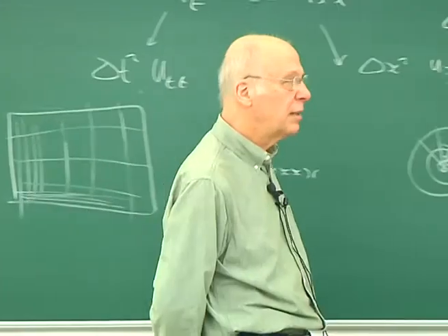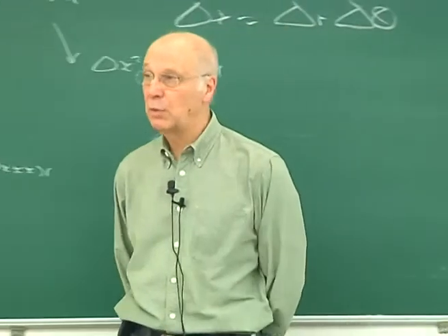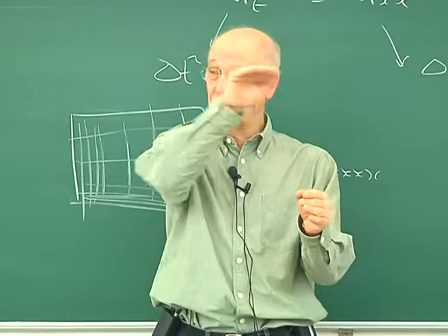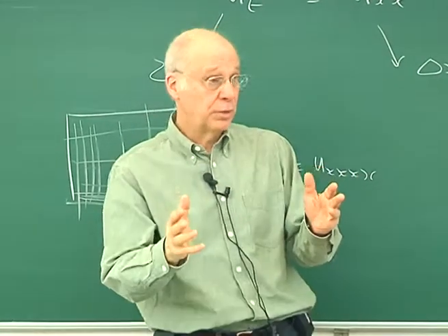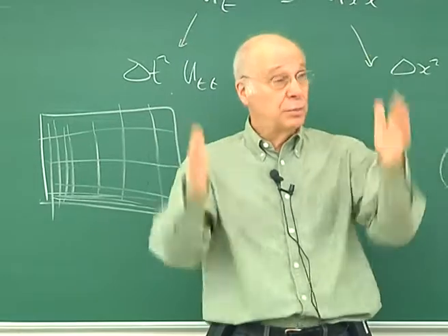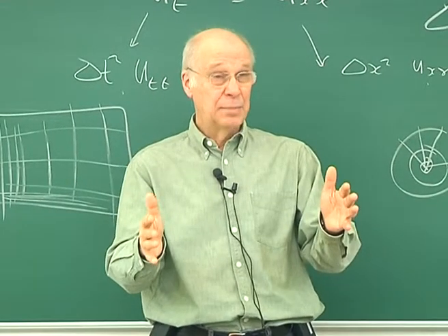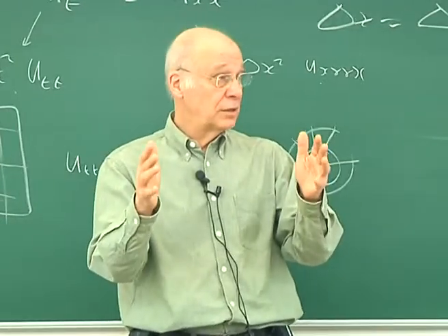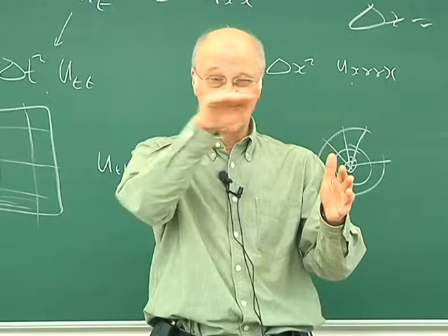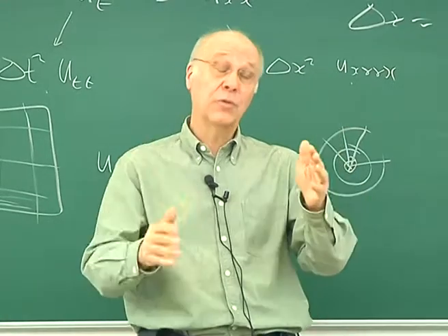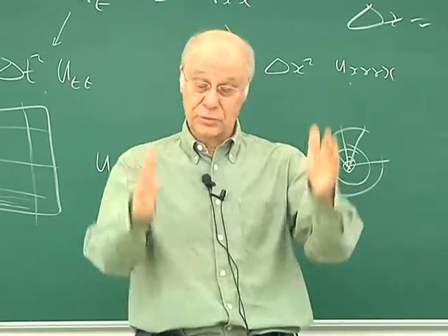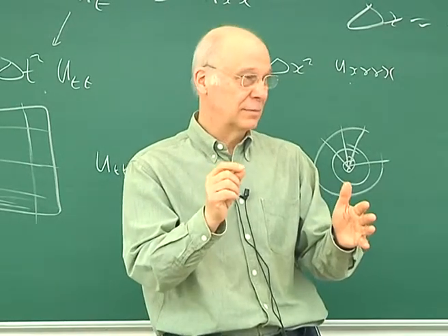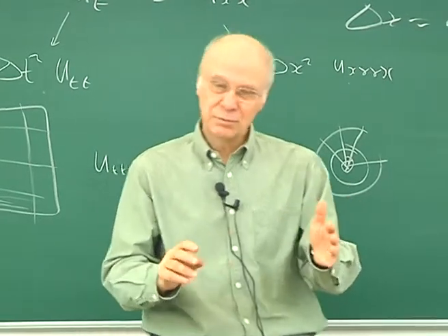Okay. There was a little embarrassment at the end of last lecture. When I worked out the force on my box, I could work out the viscous force on the top. But now, because I've got the pressure, I can work out the viscous force on the bottom. And the pressure force is on the side. Because it's a steady state and there's no creation of momentum, there's no body force, the force on the top plus the force on the bottom plus the force on the side should cancel to 0. And it didn't quite get to 0. It was within a percent of 0.